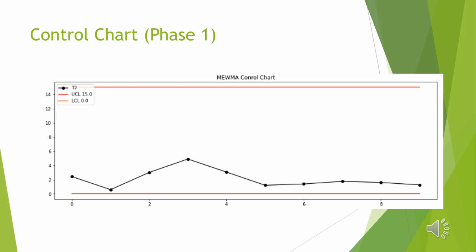Once we knew that the data was independent from the ACF charts and identically distributed, which we knew from normalizing the data was going to be the case, we were able to plot this data on a MEWMA chart, which is the chart that we chose to use for our multivariate analysis. As mentioned earlier, we use the quality characteristic of layers, making each layer its own quality characteristic, and for the 3 layers chosen, 100, 173, and 200, each of those were determined to be a quality characteristic that were rolled up into a control chart, such as this one, that could identify and evaluate multivariate scenarios.